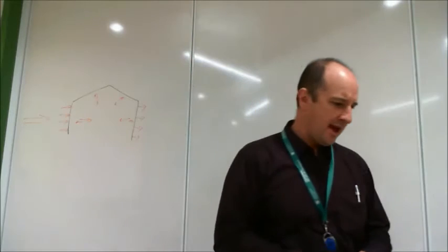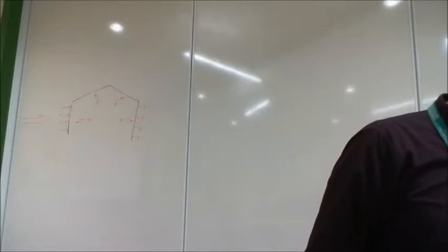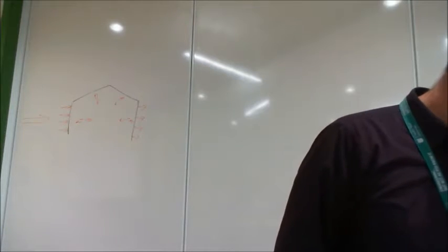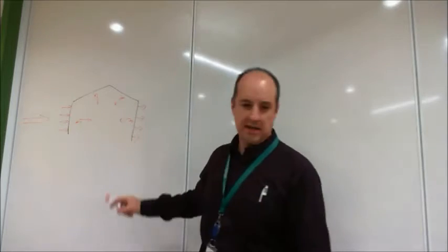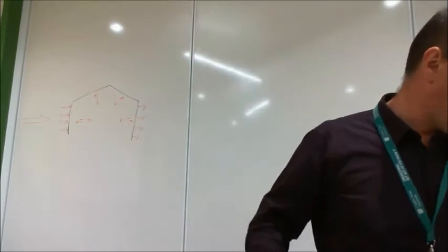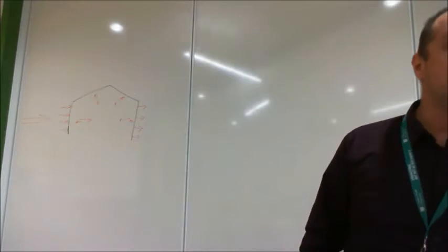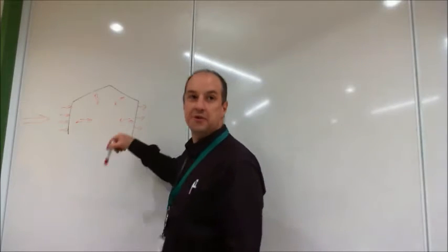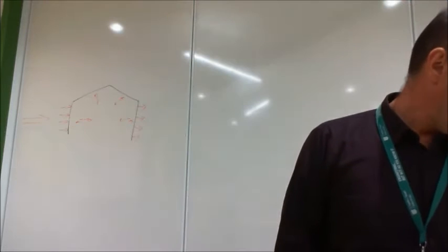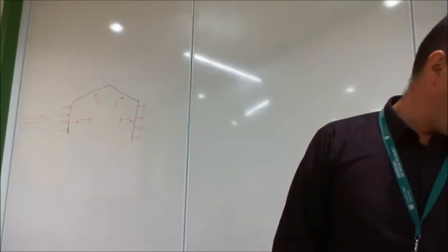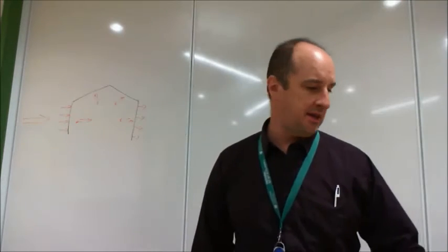Okay? And those are in tables. Windward wall is a very easy one. It's almost always 0.8. Leeward wall is another table. Windward wall is 5.2a. Leeward wall is 5.2b, and that value depends on a few things in the building, but that's relatively straightforward as well. We'll skip the side walls for the minute. I'll come back to that.